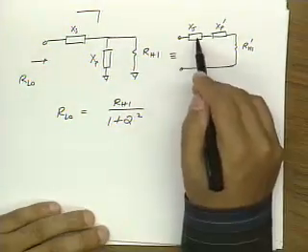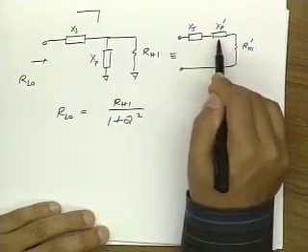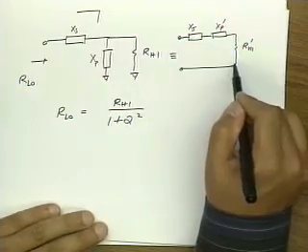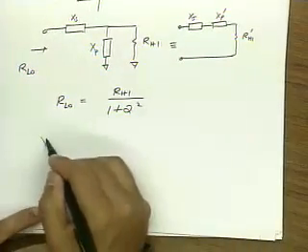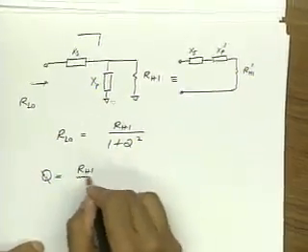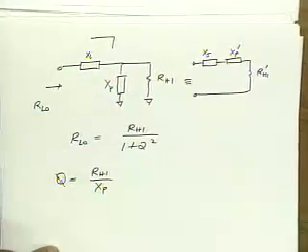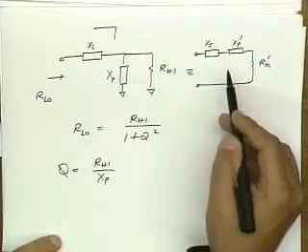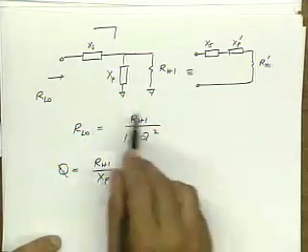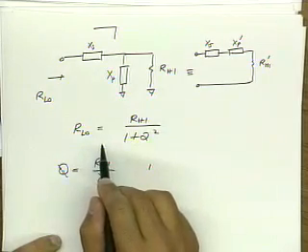And of course, we set these equal to each other and with negative signs so that they resonate out, and we just end up with R high prime. Now remember, the Q for a parallel network is R high over XP, right? And when we do this transformation, we know that this is satisfied. This is the part of the transformation.